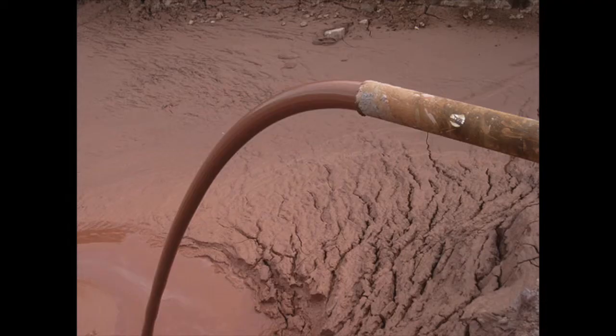Sludge is produced as a byproduct of the Fenton process. Primarily, the sludge is in the form of iron oxyhydroxides. Approximately 40 to 180 milliliters of sludge is produced per liter of wastewater treated. Biological processes alone produce significantly more sludge, and 30 to 50% of the operating cost is spent on treating it.